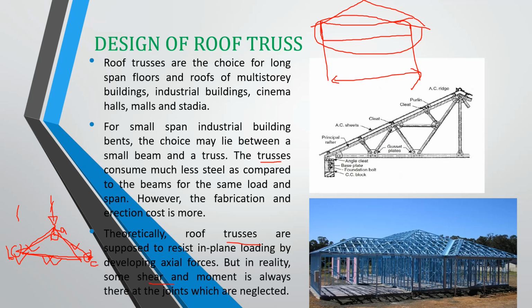If we want to compute manually, those secondary stresses can be computed by indeterminate structural analysis, but we are not concerned with that at the moment. Usually, if we do manual calculations, the amount of effort required for that computation is very large, and that amount of work is not justified for the analysis of an ordinary roof truss. So we just neglect secondary stresses. So we have touched a little upon the structural behavior of these trusses.